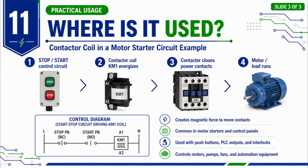contacts. In a motor control circuit, pressing the start button energizes the KM1 contactor coil. The contactor closes its main power contacts and the motor starts. When the coil is de-energized, the contacts open and the motor stops. So remember, coil energized, contactor operates, load runs.